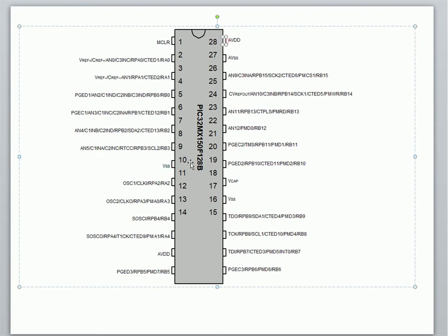And these are power connections. These are not programming pins, right? So we're never going to get to program them. They're how we connect up to things on the board. A lot of those connections are done on the Microstick 2 for us. The pins we get to work with are all these other ones.